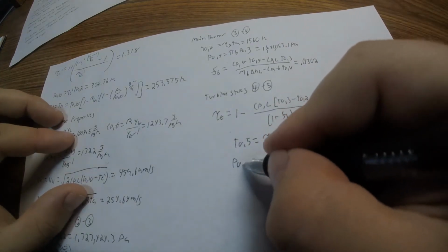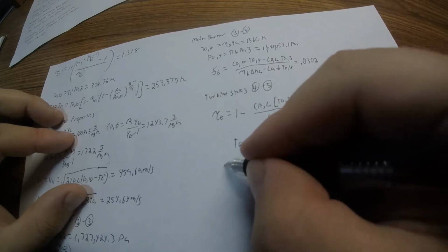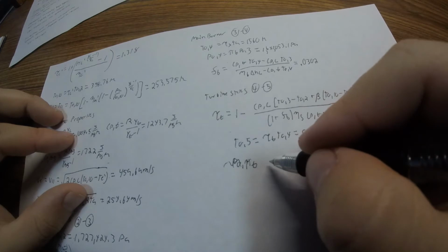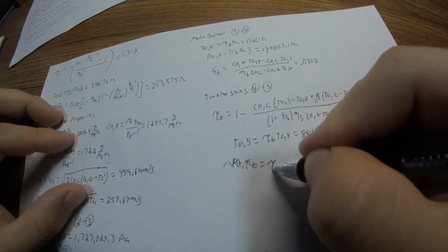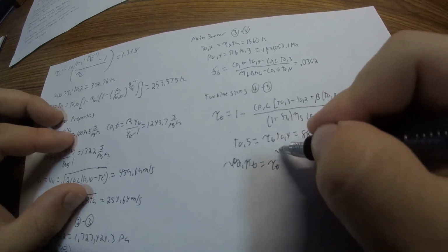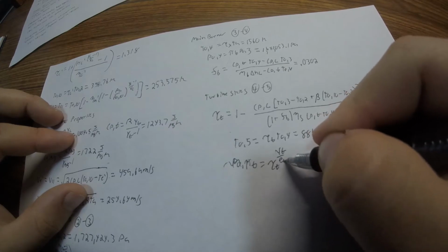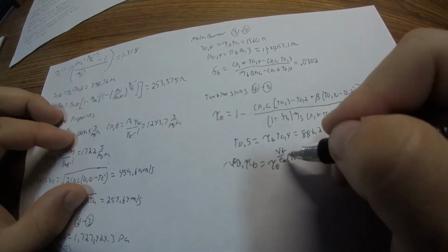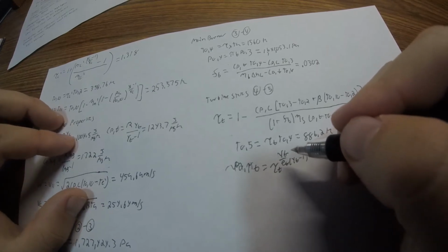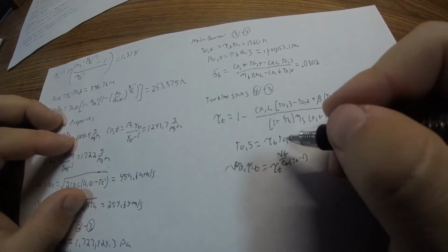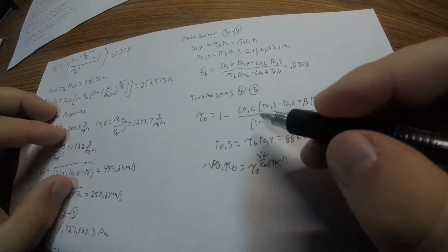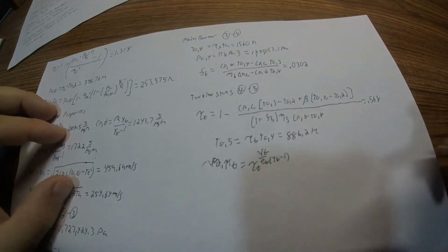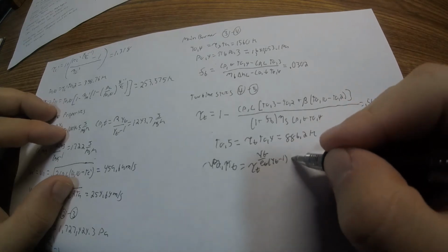Now the pressure is really going to drop here. So we'll find a pressure ratio for the turbine equals tau T to gamma T divided by the polytropic efficiency of the turbine. And now we're dealing with this new specific heat ratio value, because now the air is significantly hotter, so the properties change.